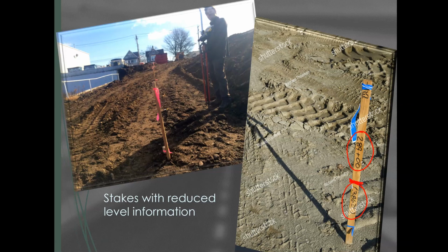So when the road builder comes, they know at this point how much they have to fill up or cut down to get to the vertical curve required. Similarly here, pegs are marked at regular intervals, and each of the pegs would have information on the reduced level.